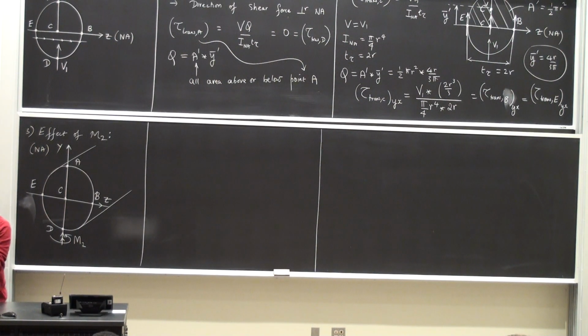Maybe not. But okay, so here this is the plane. Okay. So the way the bending moment is applied is I'm taking the screen and I am rotating it this way, which means that all the fibers here are getting pulled out, all the fibers here are getting pushed in, which means that I immediately know, without recourse to this pesky negative sign, as to what part of the cross section is tensile stress and what part is compressive stress. Does this make sense to everybody?